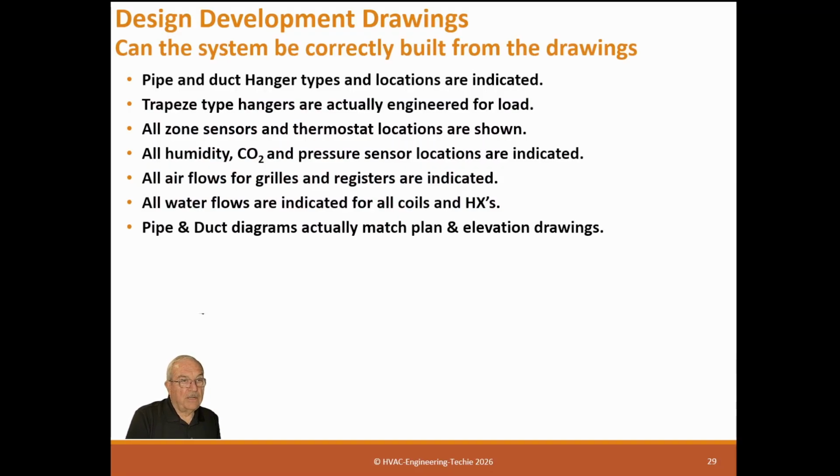Pipe and duct diagrams actually match plan and elevation drawings. Now, you say, well, why wouldn't they? Well, sometimes it gets hard. You've done a flow diagram. Oh, it's real clear there. And you go out and look at the drawing in the field and say, well, I can't figure out what's going on here, especially for headered equipment. Duct or piping arrangements, if you've got them headered together, then that's kind of critical for that.